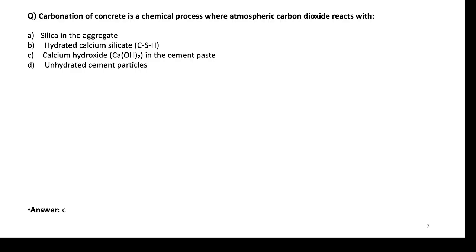However, in some of the newly developed concrete where there is very little calcium hydroxide available, the reaction of CO2 can happen even with hydrated calcium silicate or CSH structures, which can lead to decalcification of CSH structures and loss of integrity, and can lead to coarsening of pore structures and also reduction in the durability of that concrete.